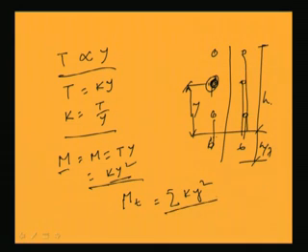So, the summation of Ky square, where i will vary from 1 to n, where n is the number of rivets. In this way MT is equal to summation Ky square. That means, in place of K, I can write T by y. So, MT is equal to T by y into summation y square.